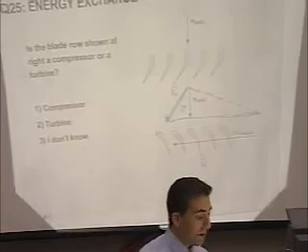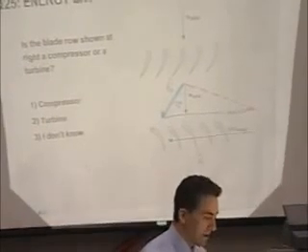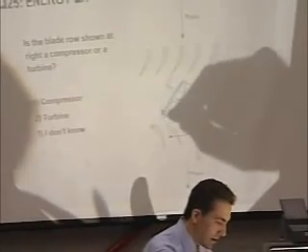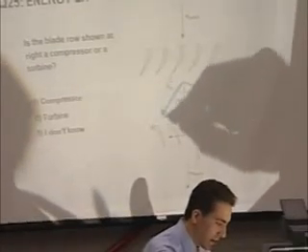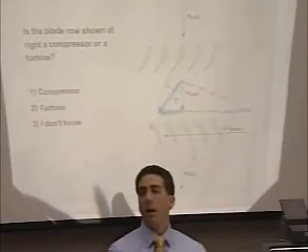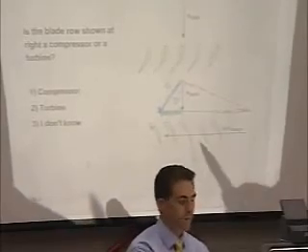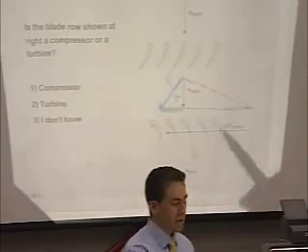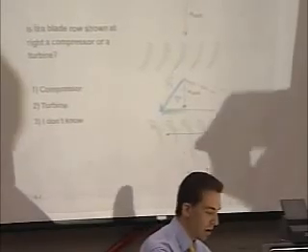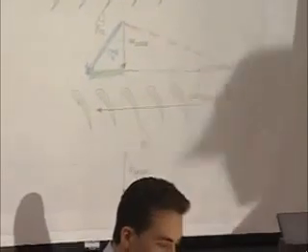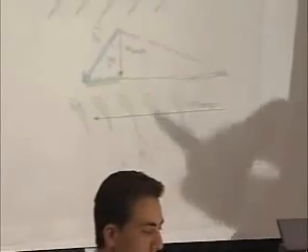And this gives me one very important thing: I also have the tangential component here in green of velocity in the stationary reference frame coming into the rotor. Now I do the same thing at the back of this, but now I'm in the rotating reference frame. So I've got velocity leaving this, following the blade angle.